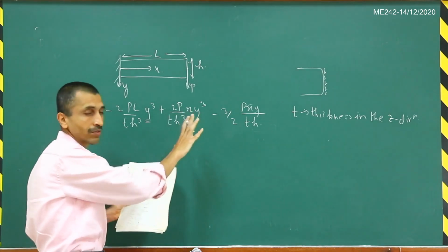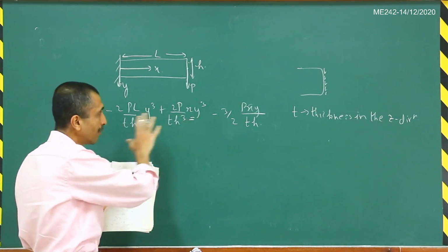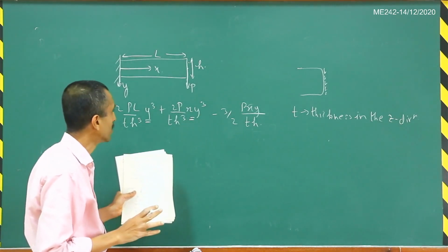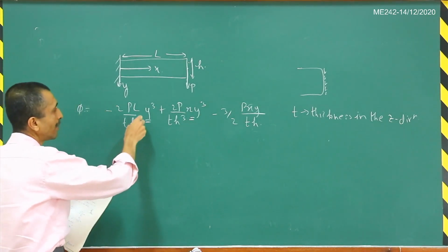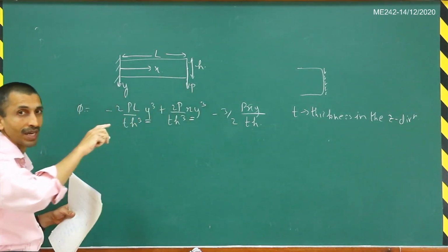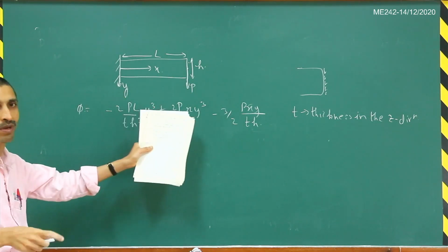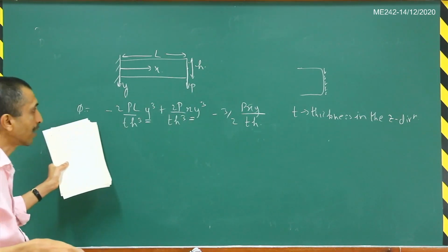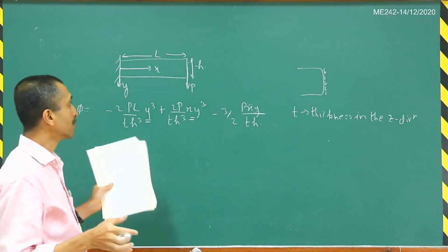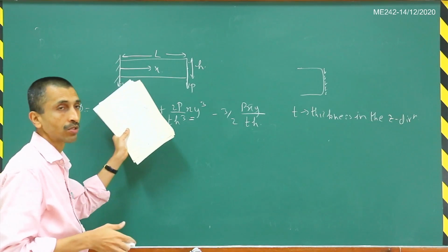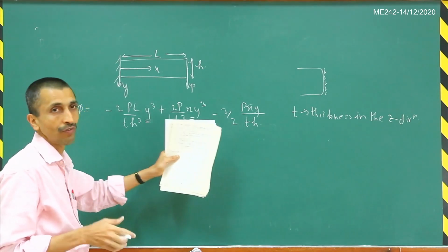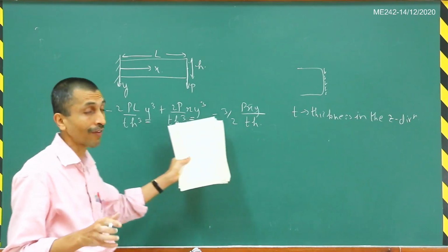So here, at least for this particular example, we try out various biharmonic functions, and then we adjust these coefficients so that the boundary conditions are met. Now, somebody has already done this job for us, and that's why I am just writing out the complete Airy stress function directly. But suppose I did not know the solution to a particular problem, then I would have to find these coefficients, or even the functions themselves.